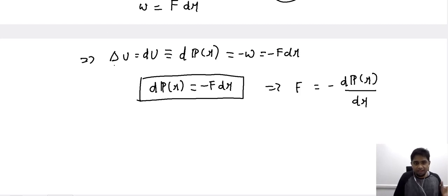So essentially we have quantified the change in the internal energy of the system with respect to the force that we have imposed. The force that we are talking about is the uniaxial tensile loading. Now this internal energy is solely governed by the interatomic potential. So when we are saying that the internal energy of the system changes, what we are saying is there is a corresponding change in the interatomic potential.